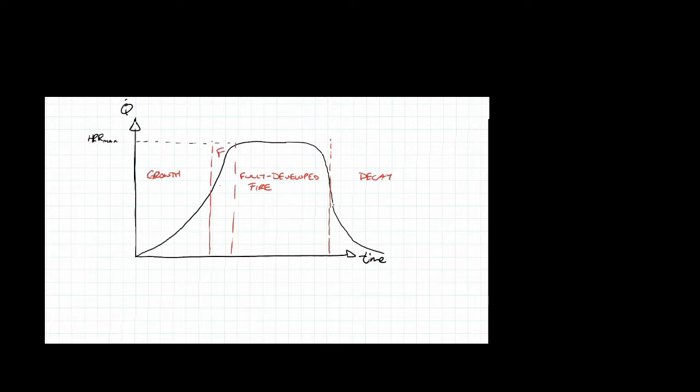The purpose in understanding this profile for compartment fires is to comprehend the principle of flashover. Flashover is that transition during a growth phase where it comes up to a point, heats up a compartment so that the compartment, at least at the floor, has basically a 20 kilowatt per meter squared heat flux. And realizing the smoke layer that's basically formed at the ceiling is about 600 degrees Celsius. It produces a huge amount of radiation.